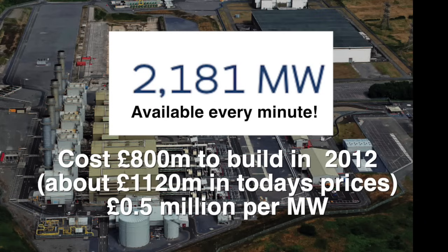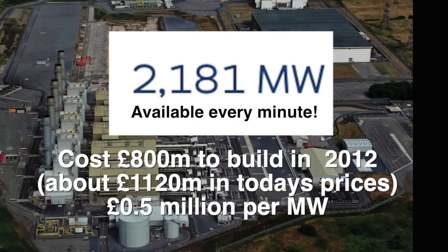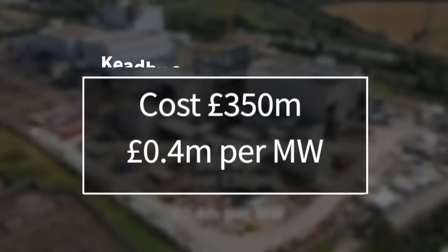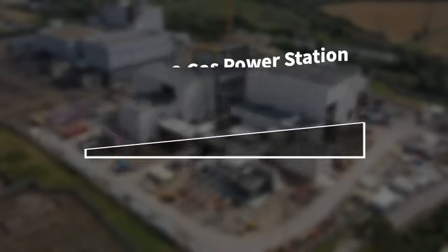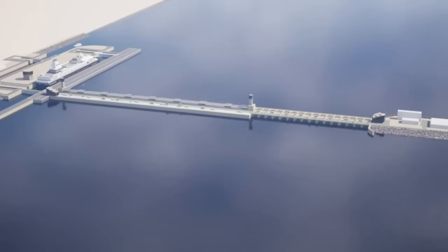And that comes down to £500,000 per megawatt. But just as a cross-check, let's flip over to a much later one that's just been built and check what that's costing per megawatt. Well, there it is. Keadby Power Station comes in at £0.4 million per megawatt. That's a more recent and more accurate figure. So we'll take that one, but I'm just trying to give you a general guide as to what normal gas power stations cost.